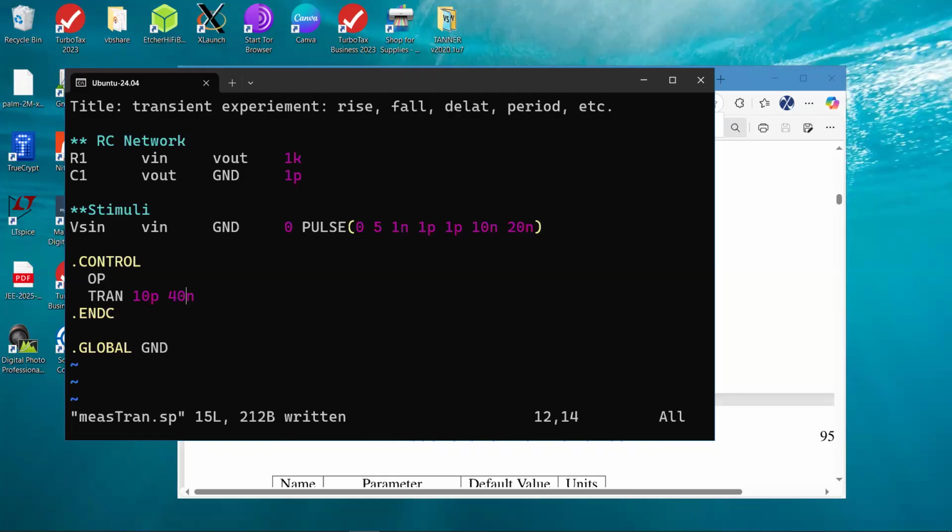See, for the DC operating point, you should always have a DC voltage. It probably takes this as the DC voltage, but put that value, so that when you're doing the operating point, you're sure that that's the value. Like in Xspice and Spectre, you have to actually put that value, but maybe here it's not necessary. But DC value, always put it. That's a good habit to be in.